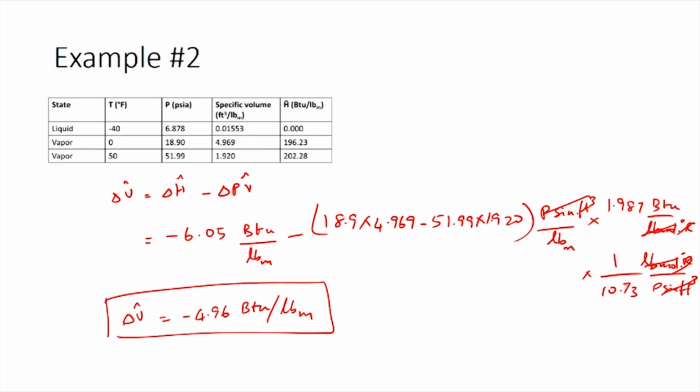So, the third part of the question asks us to identify the assumption that has been made. So, we have calculated specific enthalpy values without actually knowing the pressure of the final condition, which means we have assumed that the change in specific enthalpy was independent of pressure. So, this is a reasonable assumption to make for any small changes in pressure, because it is a gas and we can assume ideal gas behavior.